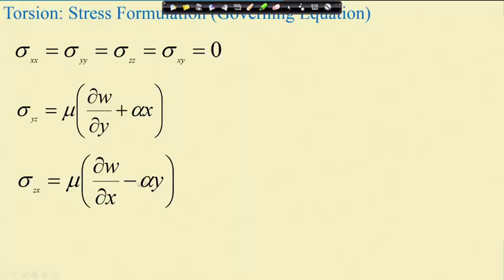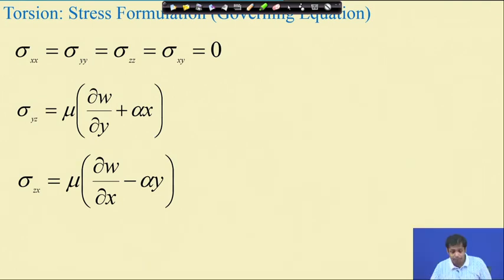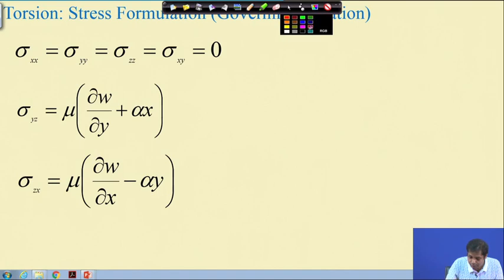Now, if you look at these 2 equations, what is it essentially? These 2 equations essentially have the definition of strain, the strain-displacement relation, and in that relation we replaced strain by stresses, and we have these two equations. Now let us combine these two equations. If we combine them, first you take the first one, the yz, let us differentiate this one by del x, and then differentiate this one by del y.